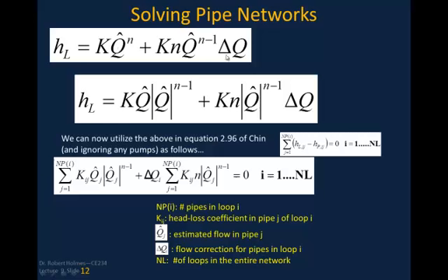And then on this side over here, I just say that the Q hat is always the absolute value of. That way I'm using this first term to set whether the head loss is positive or negative depending on which direction I'm going. All right, and then I'm going to utilize the conservation law where I've summed the head losses around the loop, which I've written out to you.